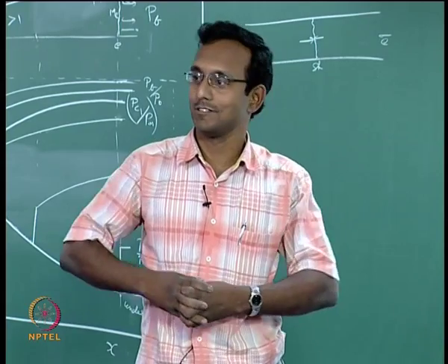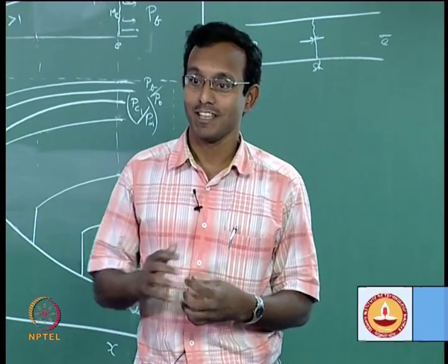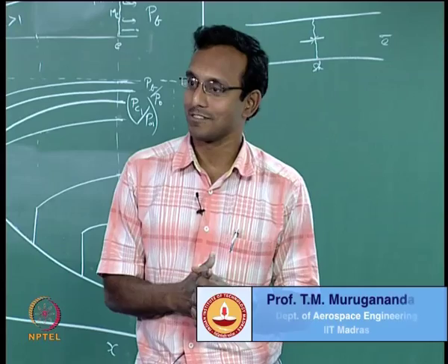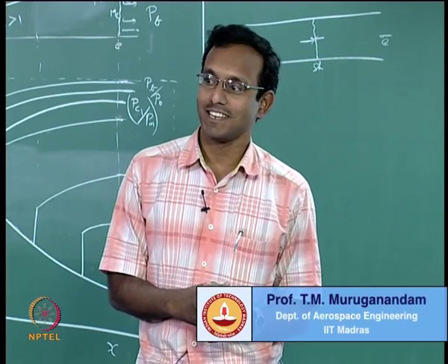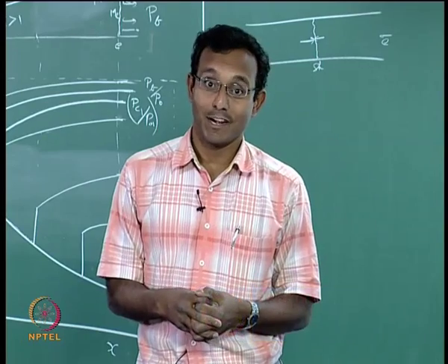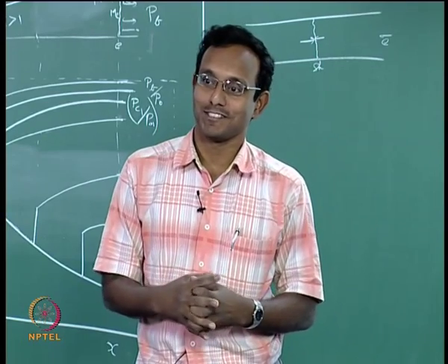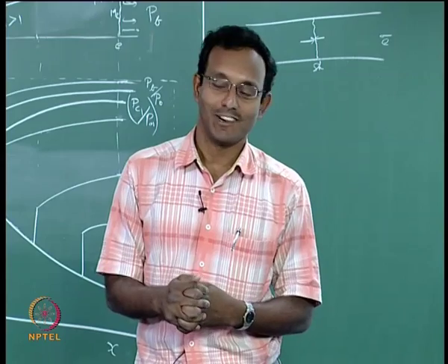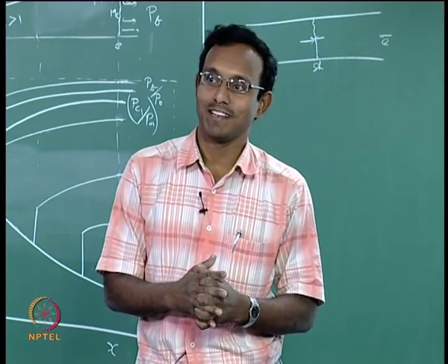Back pressure is continuously decreasing, which means the strength of my shock should increase, right? That is what we have been discussing till now. In fact, the Mach number at the shock is higher. We are seeing that the delta P is lesser, and I know for sure there is nothing wrong in my calculations. Is that logical? Can we explain this? That is the basic question.